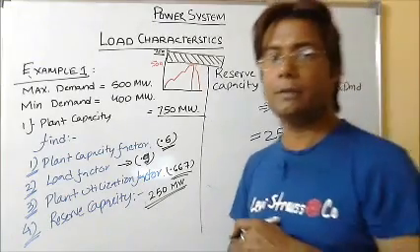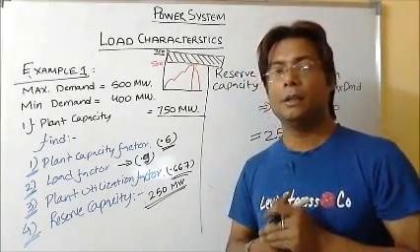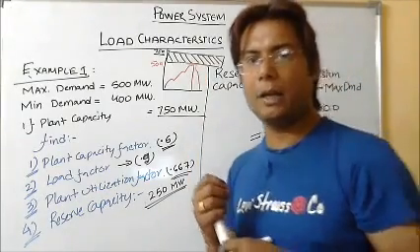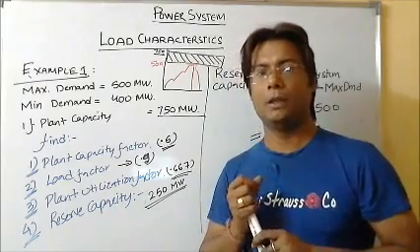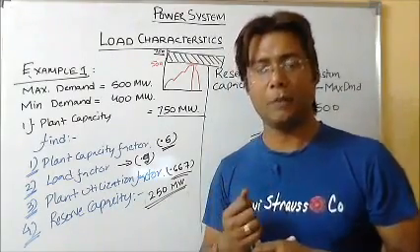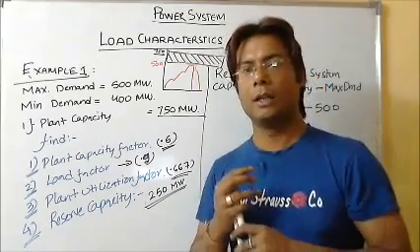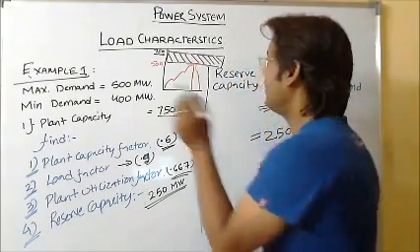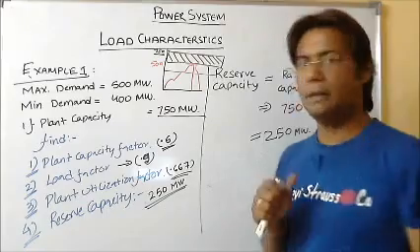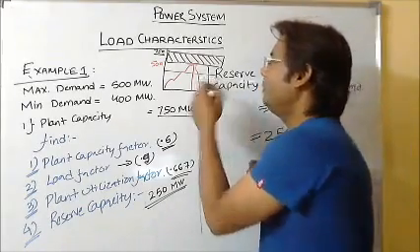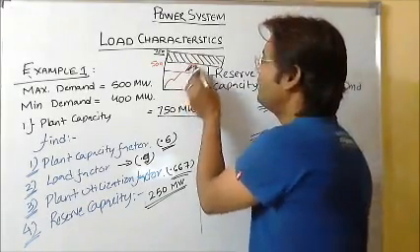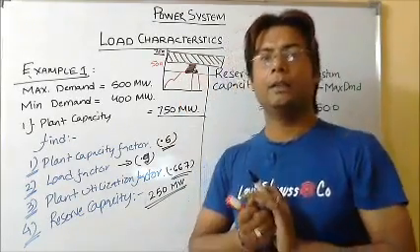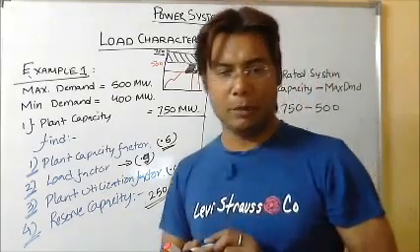So this is what we can understand from this question: if the maximum demand is lower than the reserve capacity, I will have surplus power. If I want to produce some more electricity or some more power, I will be able to produce beyond my maximum demand. If my reserve capacity is not there, then it may be possible that I have to take the amount beyond this line from some other interconnection, and I will not be having any reserve capacity at that moment.